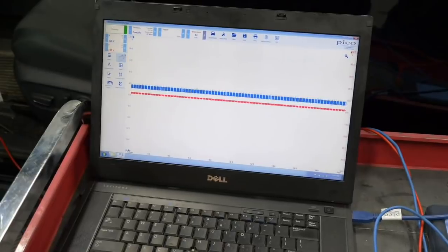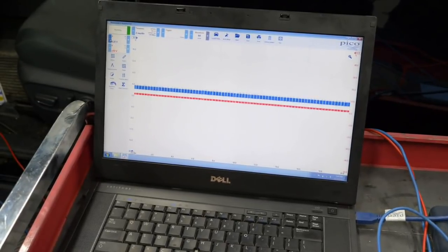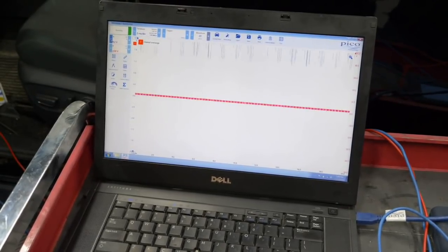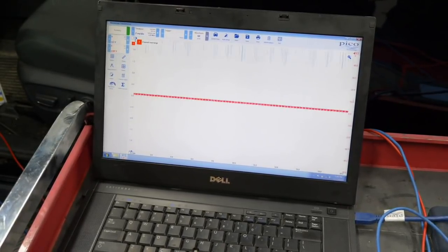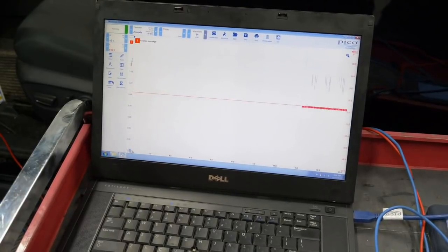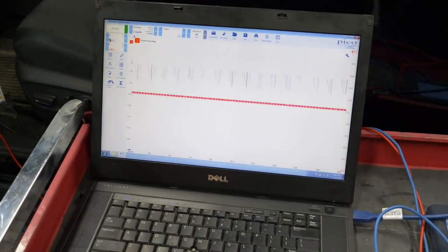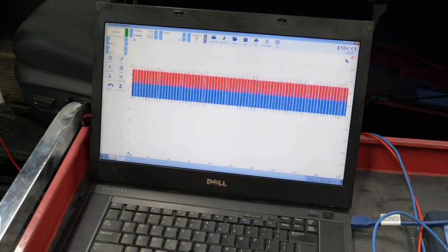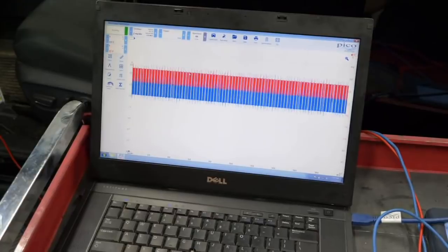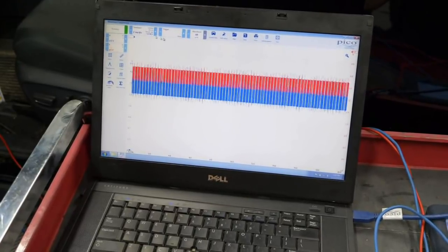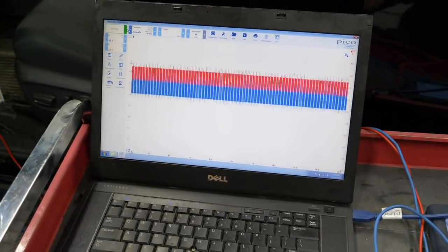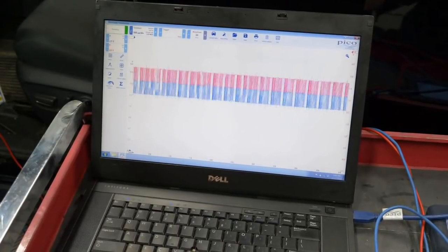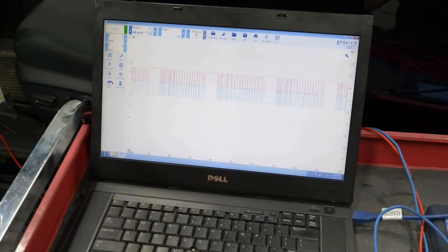All right, so we can see I've got some messages here, but I am far from optimized right now. So one of the things, my voltage setting for CAN signal, we know we want to be considerably different here. So probably around 5 volts is going to be optimal. Means I got to bring my channel B down 5 volts for my opposing signal. We are running very fast right now, so we need to separate out our signals.